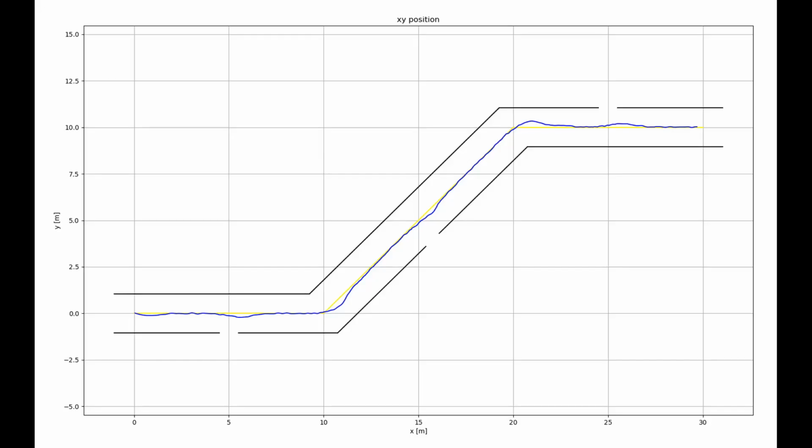The resulting X-Y trajectory inside the horizontal part of the tunnel environment can be seen here. Smaller tunnels connected to the main tunnel will make the drone drift towards the wall because the repulsive force is smaller there. With some better controllers, the performance could probably be further improved.